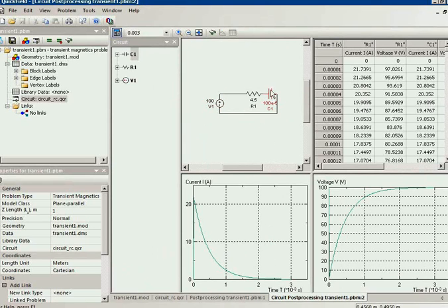You can see how the capacitor voltage changes in time. The capacitor is charged till it gets the full charge at 100 volts. And our estimation was correct at about 3 times of the time constant at about 1.5 milliseconds.